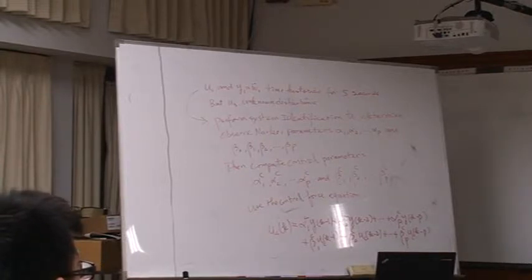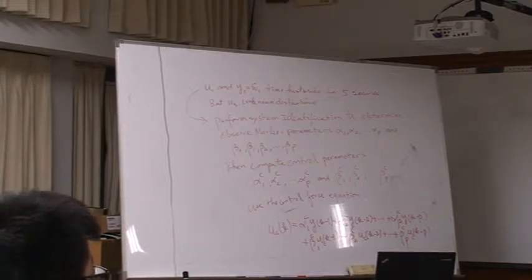Then after that, we turn on the controller. You can see that after we turn on the controller, from about 0.7 second to 1 second, it becomes quiet. Although you still see some responses here, because that disturbance is still on. You still have a disturbance, just like the earthquake is still on.